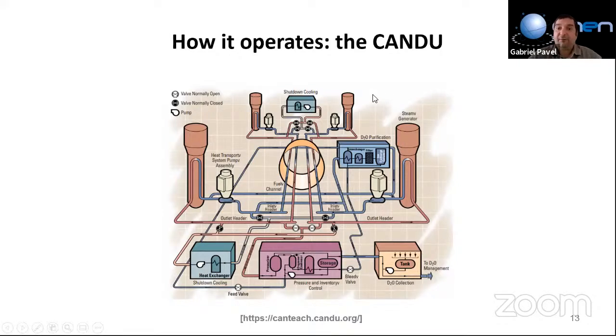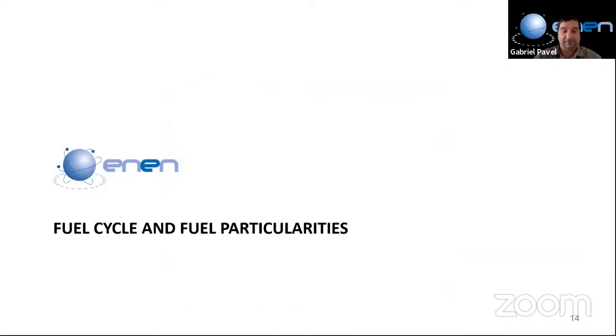You see here, in fact, there are 4 steam generators and 2 identical loops. Half of the reactor has one loop assigned and the other half the other loop. So you can have 380 fuel channels. Half of the 380, so 190, are assigned to 2 steam generators, and 190 are assigned to the other 2 steam generators. All the steam generators are designed to withstand more than the normal heat capacity produced by the reactor itself. Okay, I need to speed up a little bit.